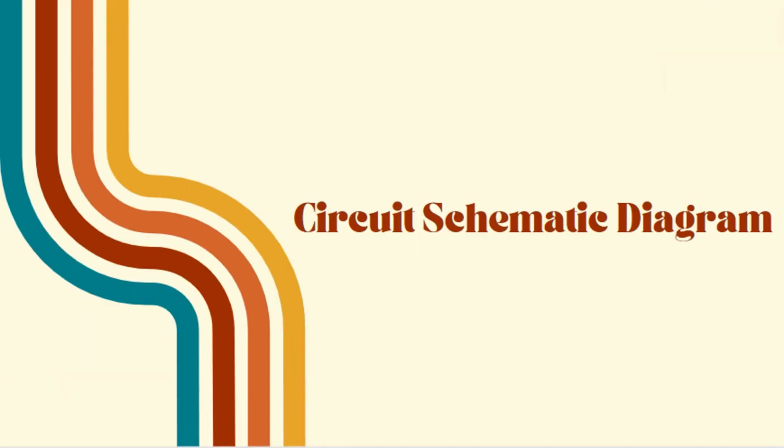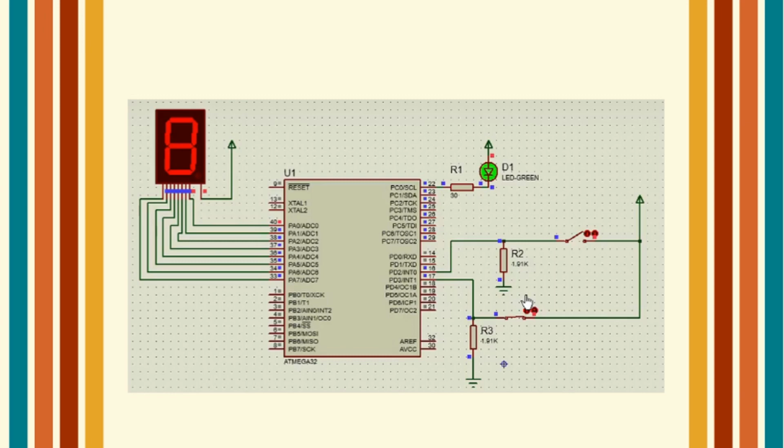Circuit schematic diagram. We connect the 7-segment decoder, common anode, to port A, and the green LED in active low configuration to port C, which is PC0. Our sensors we replace with switches, so we connect them to interrupt 0 and interrupt 1, which are PD2 and PD3 at port D. These two switches or sensors are in active high configuration.